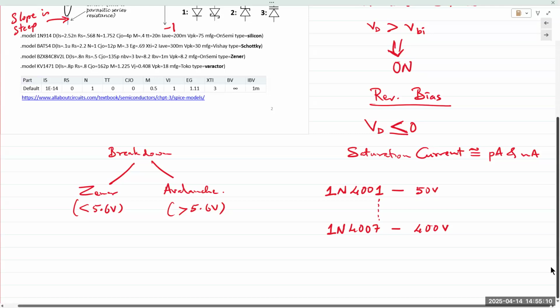And because of the high value of this electric field, the electrons acquire more energy and they're moving in a haphazard manner, random movements. As they're moving, they'll collide with other atoms in the semiconductor structure. When they collide with the other atoms, more electrons are now freed up. Those electrons are again subject to that electric field and now accelerated through the junction.